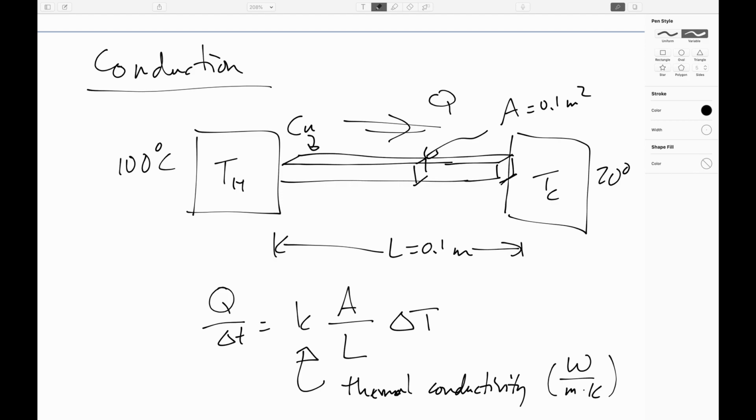And this is because the electrons are bound to particular molecules, so they're not just free to hop around. You need to have molecule by molecule collisions, which is not as efficient as having electrons getting knocked around. So that's part of it. But another part of it is that the nature of the fiberglass also traps a lot of air. And it turns out that air is actually a pretty poor conductor of heat if it's not allowed to move around.